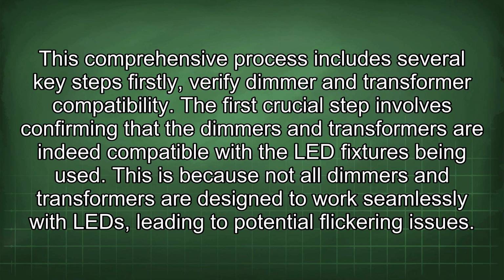Firstly, verify dimmer and transformer compatibility. The first crucial step involves confirming that the dimmers and transformers are indeed compatible with the LED fixtures being used. This is because not all dimmers and transformers are designed to work seamlessly with LED, leading to potential flickering issues.